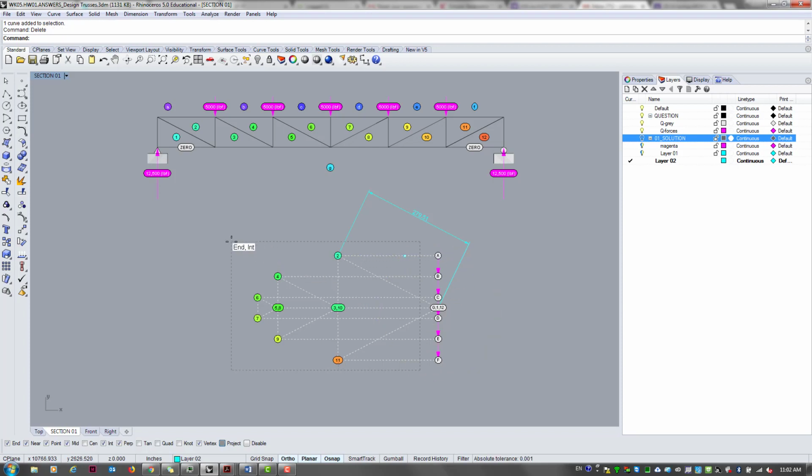And then I'm just gonna turn the control points on for this dimension. And then I'm gonna grab this whole thing, scale 1D, and then it's 150. But if you try to, right, because everything is just changing in this direction, it's not moving in vertical direction. So that's basically what you want to do. So this one was a little bit tricky, but it was recorded, so it should be fine.